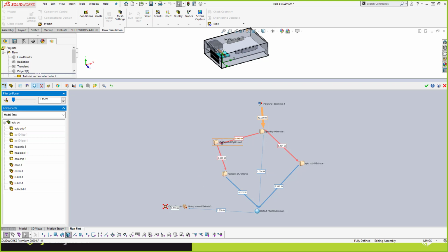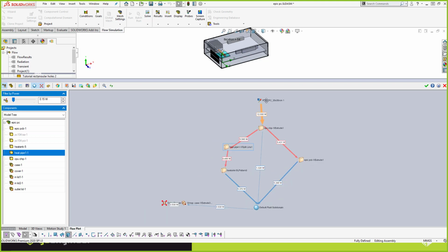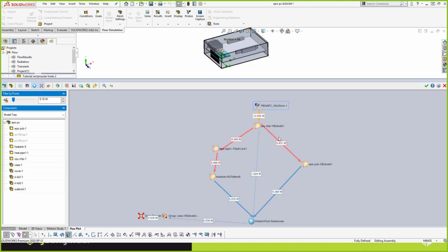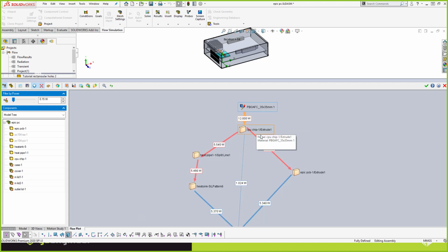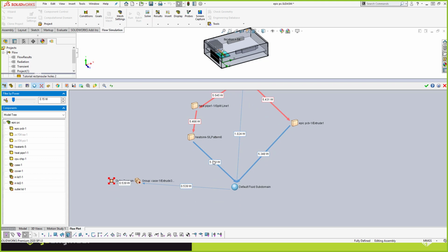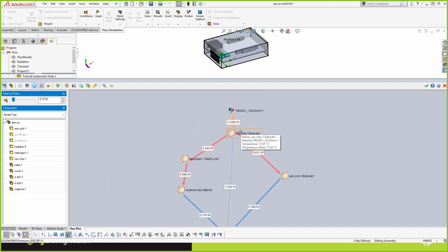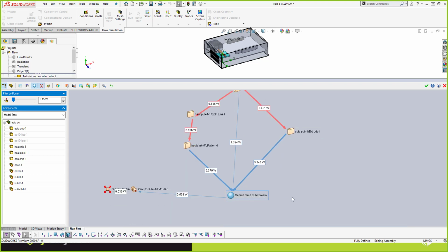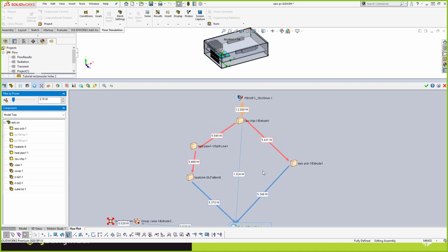Okay. So here's the overall thermal pathway. You can see the heat enters into the junction of the chip. Then it goes to the left and to the right, actually equal amounts, it looks like. So about half of it goes left, to the heat pipe, to the heat sink, ultimately to the air. And then the other half goes to the right, to the PCB. Okay, then to the air. You can look at those thermal pathways and try to optimize your model around these.